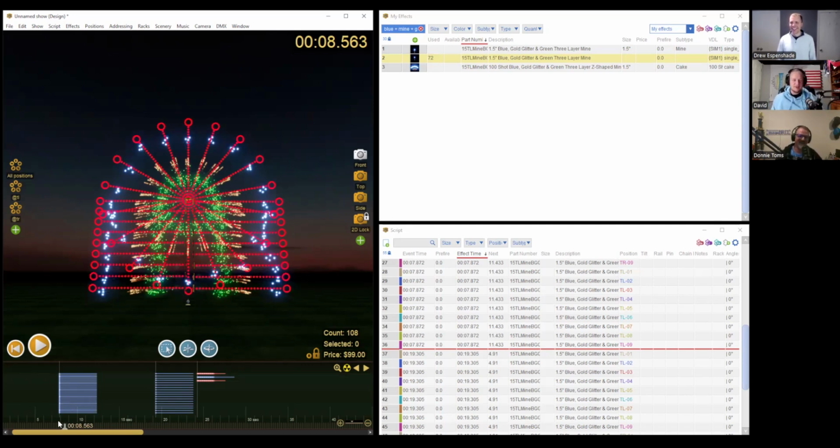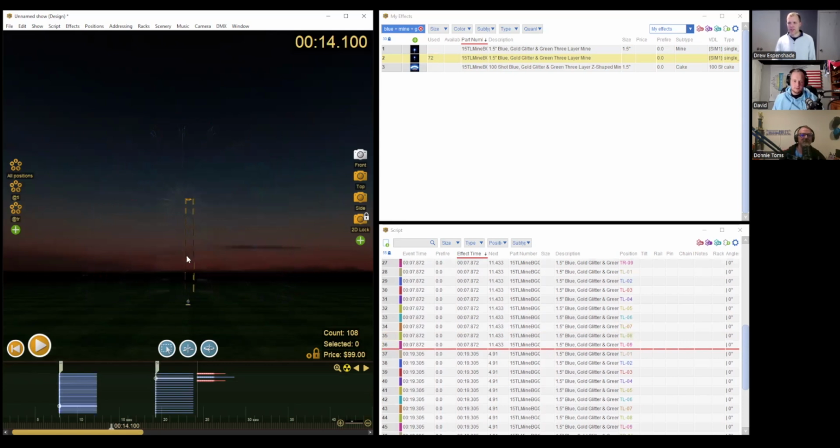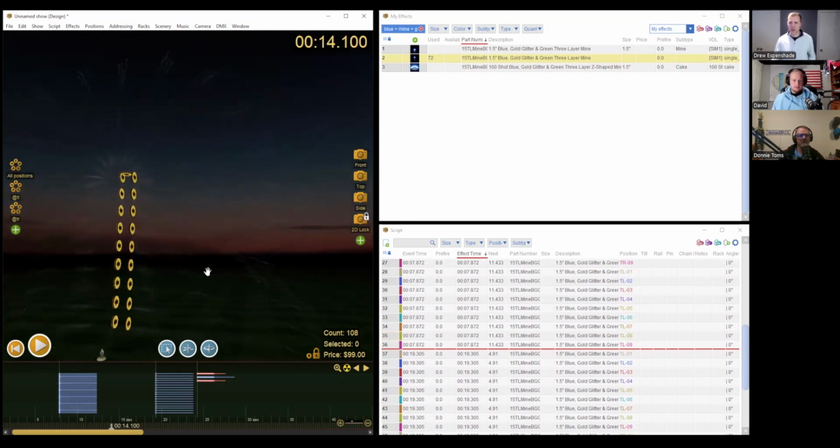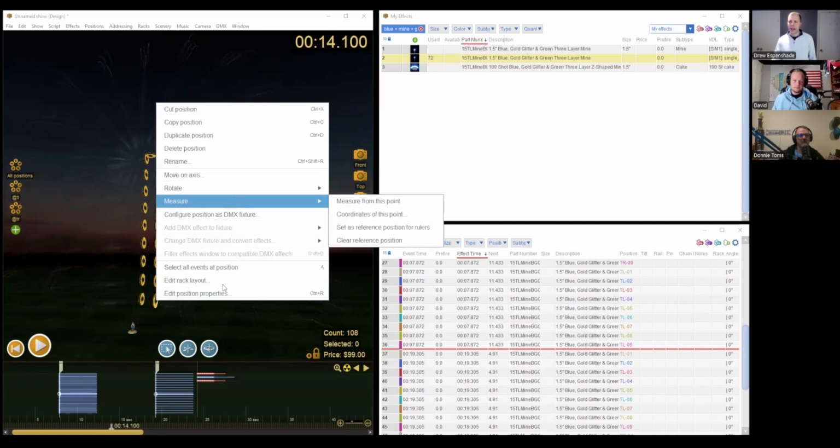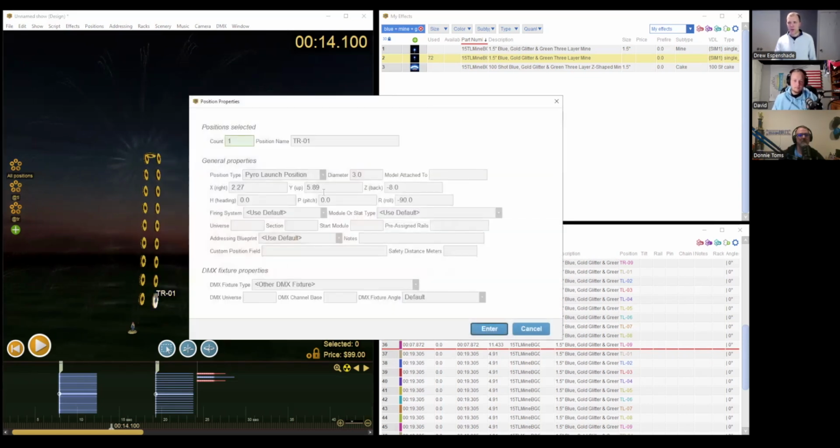I dragged each one individually. I would not discourage you from doing positions individually, and sometimes that's necessary. But a trick you can use is, instead of dragging and dropping individually, try editing each position's coordinates. If you're just trying to put them vertically above each other, they should have the same X, that's left and right, and the same Z, that's forward and back. And it's just a matter of incrementing. I know it's in meters.